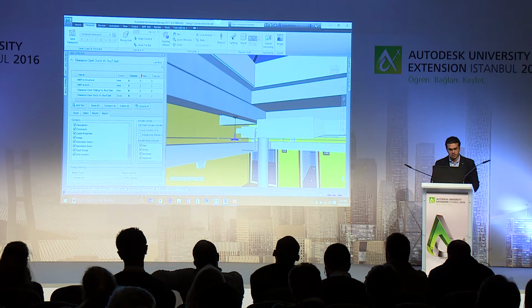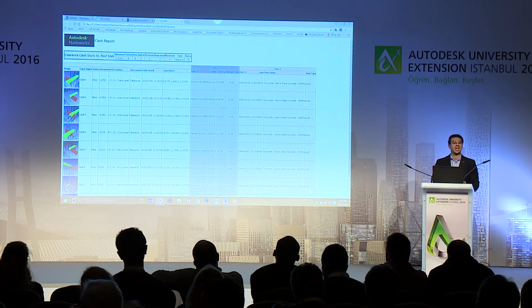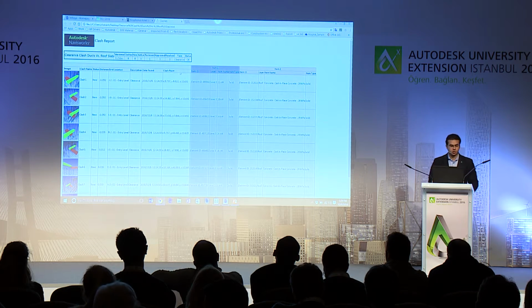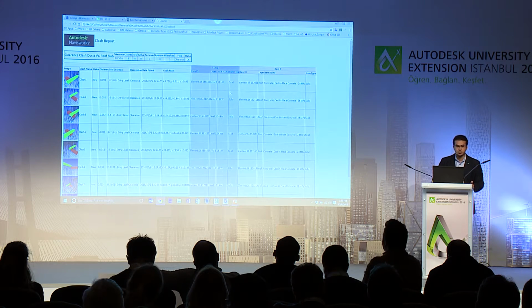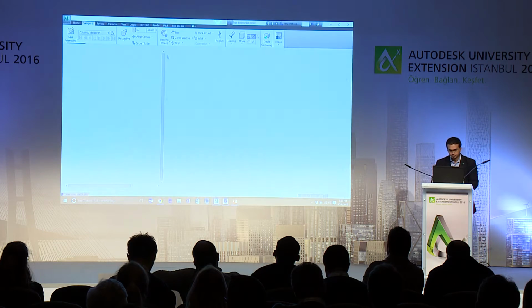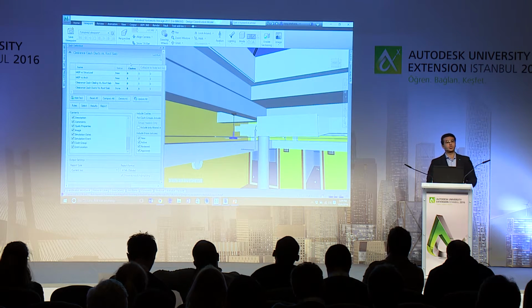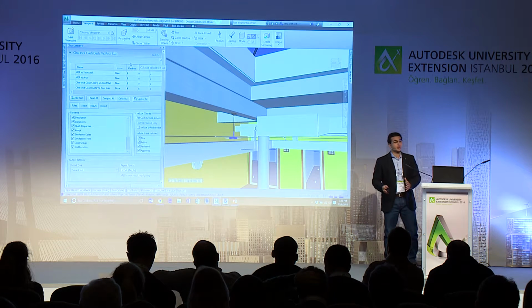And Navisworks will directly export this current test here. And this is my current clash that can be opened in any web browser very easily. So you can see here the amount of information varies. You have a very detailed report. You have even the snapshots that come with each clash. And if you added a red line or markup, it will be reported here. OK. That was related to the advanced clash detective management that can be done in Navisworks.